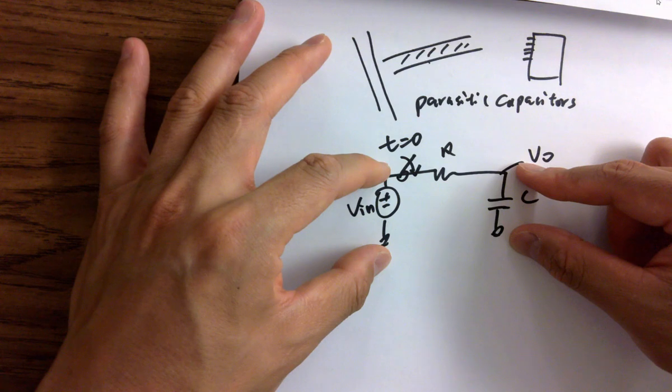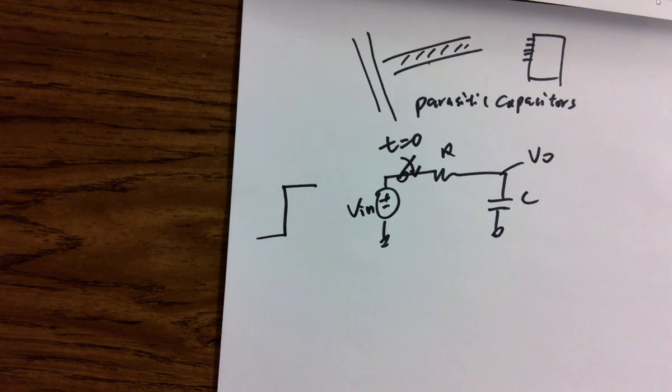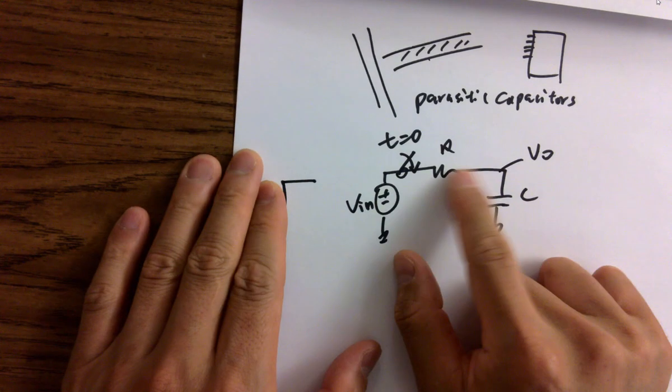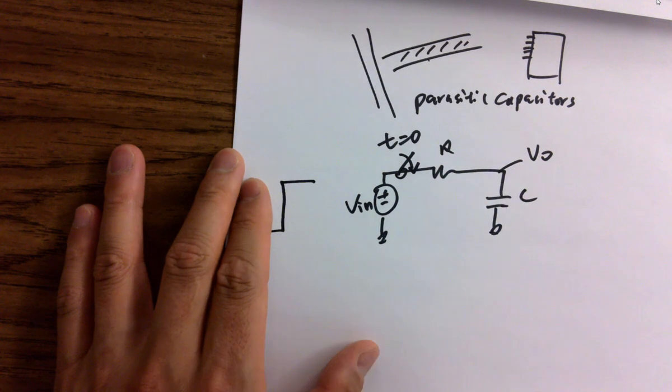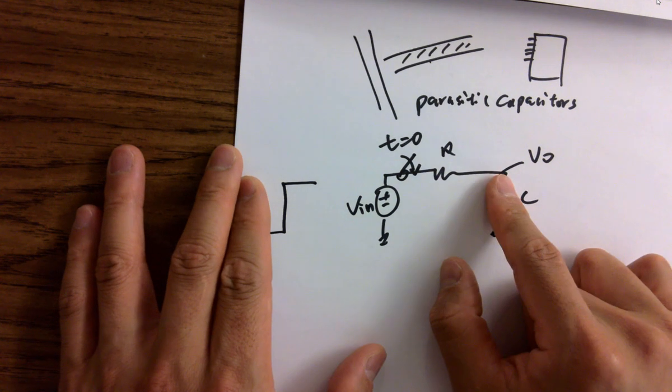Depending on the capacitor, and depending on your life expectancy, I think, the charge time can be super long. But eventually, it will be charged up to the full voltage of the input, no doubt. And eventually, there will be no current going through the resistor. In digital circuits, this happens in nanoseconds.